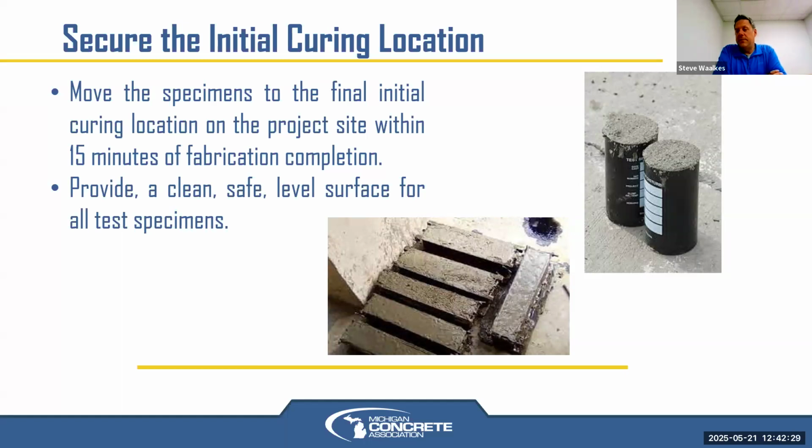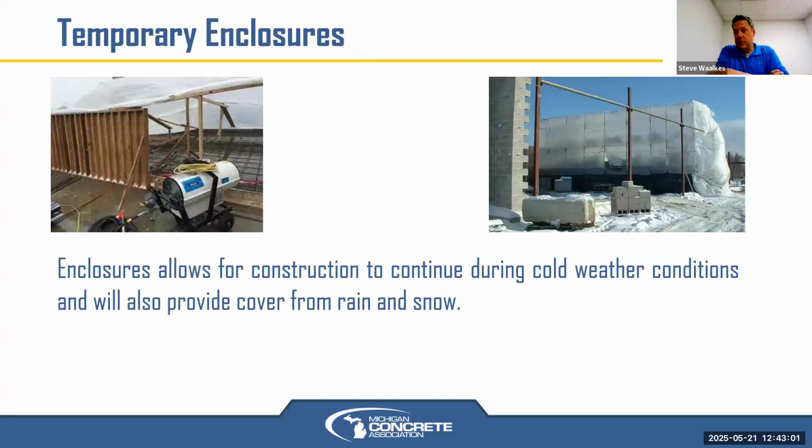So typically they're left in the field 24 to 48 hours, but usually picked up the next day or less than 2 days later. But for that initial curing in the field, they have to be moved there within 15 minutes of when the cylinders have been fabricated, or the caps put on, if they're cylinders in this case. Then they're moved to that initial location, and then they're allowed to sit and set and undergo the hardening process, at least the beginning of it. And that has a lot of requirements for that initial curing.